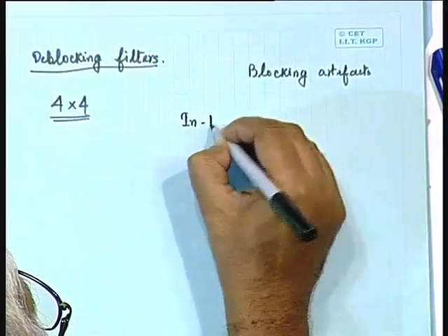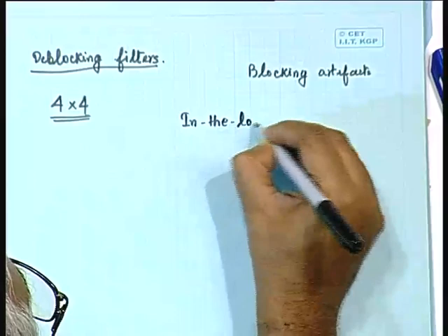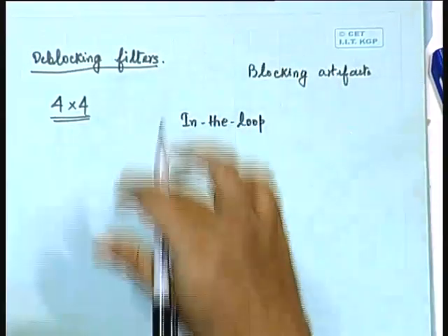Okay. So, for this the H.264 standard has specified what is called a deblocking filter, and in fact the deblocking filter is there in the encoding loop itself, and that is why it is also referred to as in the loop. In the loop means within the encoder loop.